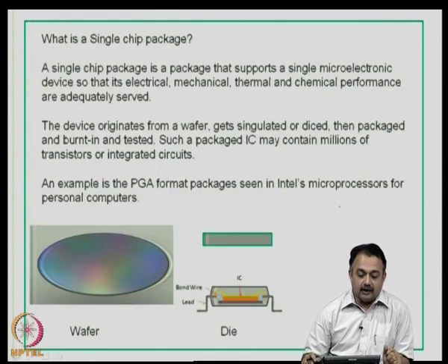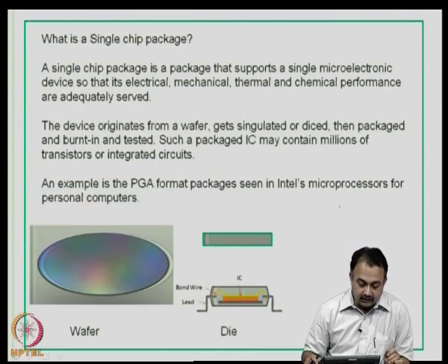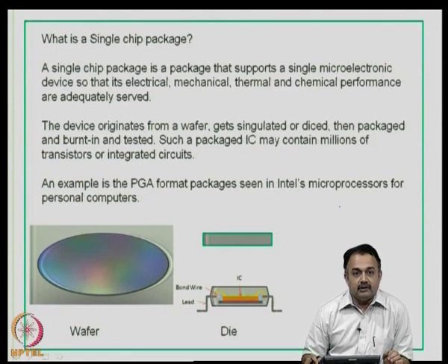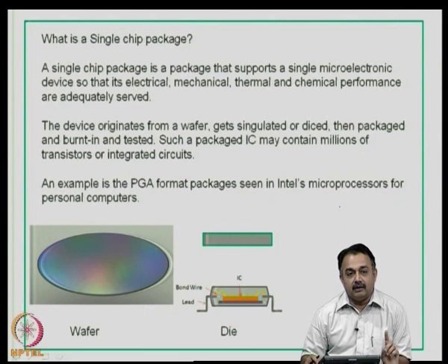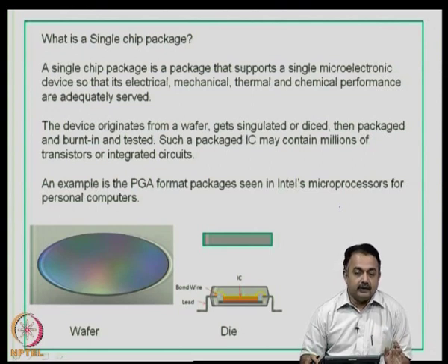So, we will try to define further what is a single chip package. A single chip package is a package that supports one microelectronic device, so that its electrical, mechanical, thermal and chemical performance are adequately served. So, it is not enough that we take a base platform like a substrate. It can be an organic substrate or a ceramic substrate or some other substrate that is suited for that